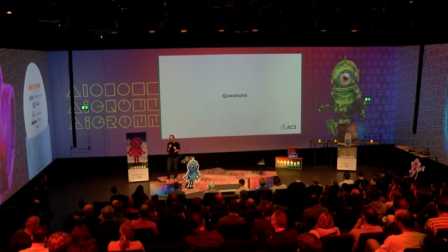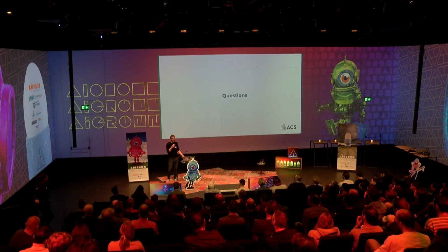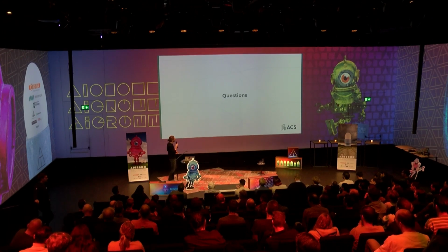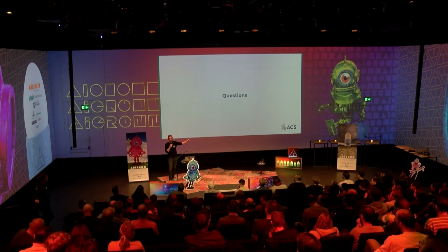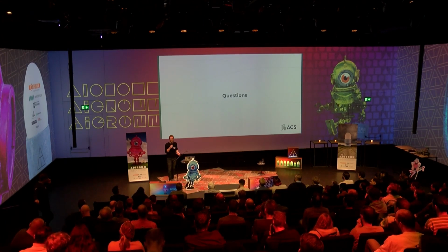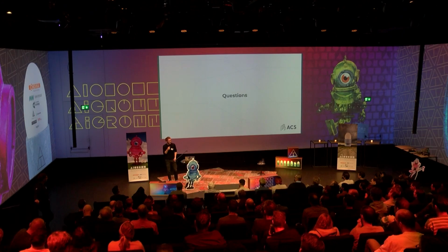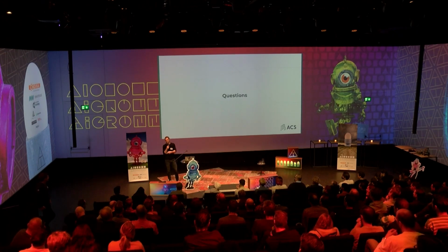Because if you have a platform and you say, hey, I have a conference room, you know that a lot of people will come, and you see that from 8 to 10 people will come there, then you should know that CO2 is having an impact. So we have made models for simulations, and there, when we have it, we always include CO2 because it really has a big influence on the temperature, also in gyms, for example, where people are, and it really takes up the temperature. So it really makes a difference. But for our modeling, we generally don't use it because it's more a problem of set points and schedules. Yeah, clear.